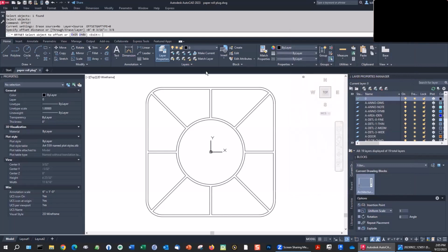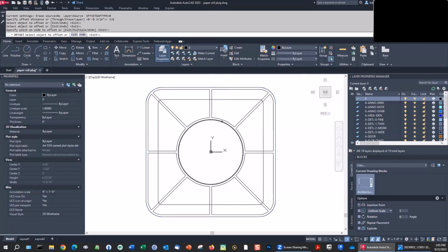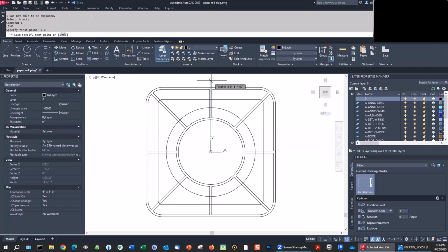From my measurements, I know that all the flanges are 3/8 of an inch thick, so I'll offset first the outside and then the inside perimeter to get those. Then draw a center vertical line again, which I can offset 3/16 of an inch for half of the center flange. And a 45-degree one for the angled flange, and offset it the same amount. Then create the first hole by filleting the edges with what I eyeballed to be a 1/8 inch radius and trimming or erasing any excess.